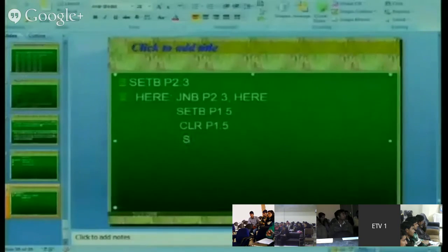So what you have written in the program is that once it becomes high, you have given a buzzer. After giving the buzzer you forgot and went to sleep. After that, when it became hot again, the buzzer was not sounded. So again you have to continuously monitor it. So S jump. Now what should be the destination of this S jump? Here. So automatically what it will do is that after giving a buzzer, it will again monitor it.